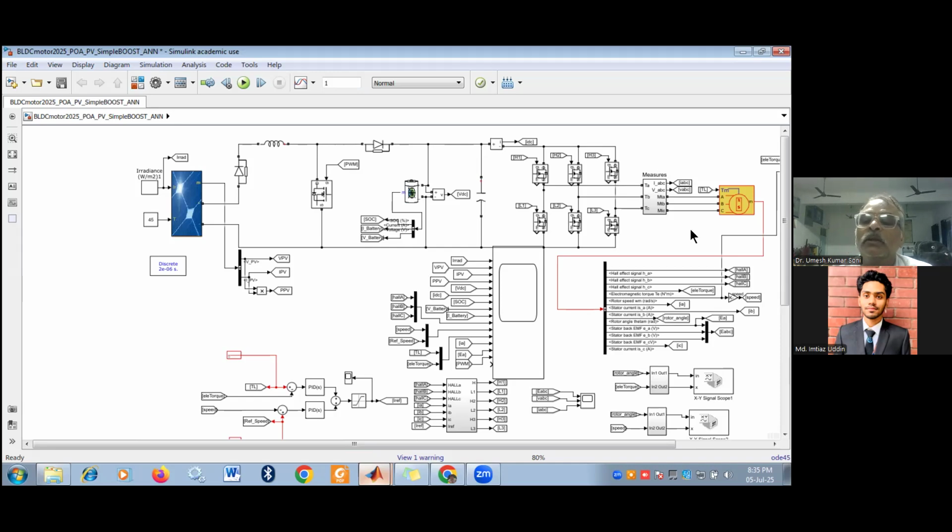Based on that, if our motor is continuously taking the rated voltage and the rated current, then the battery's capacity should be such that it can provide that much current for that time. Suppose we are driving a car for 3 hours and we have a continuous 20 ampere rating of the motor; for 3 hours we need 3 into 20 ampere hours.